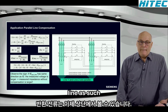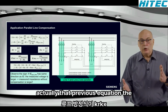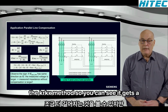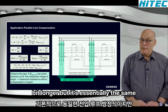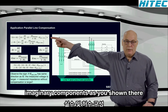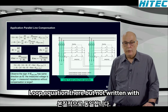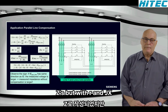At the top, you can see now that's actually that previous equation, the voltage loop equation, extended now into the KR, KX method. So you can see it gets a bit longer, but it's essentially the same thing. You can split the real and imaginary components as shown there in the two tops. That's the same voltage loop equation there, but not written with Z's, but with R and jX as such.